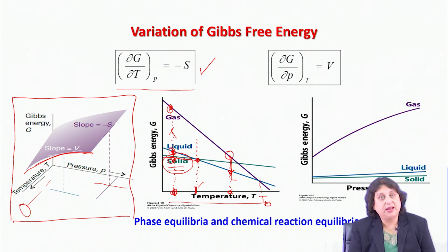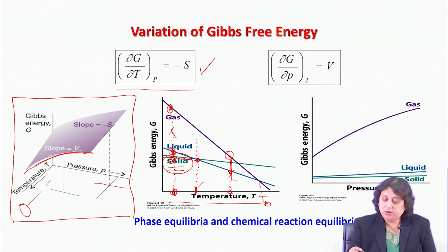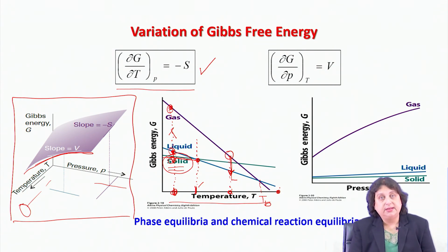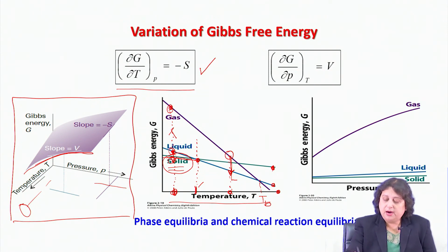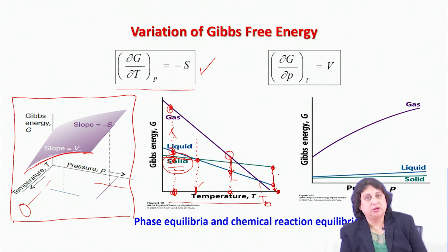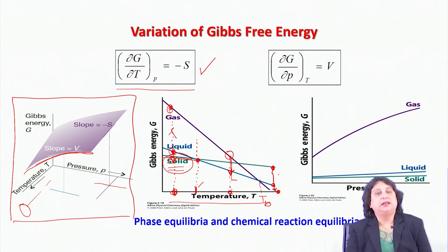because in that direction it will decrease its Gibbs free energy. Now, if I talk about a temperature somewhere here which is higher than the boiling temperature, in that case, even if I create a superheated solid or a superheated liquid here, they are going to undergo a spontaneous change in state upon perturbation to have the lowest possible Gibbs free energy by getting converted into the gas.